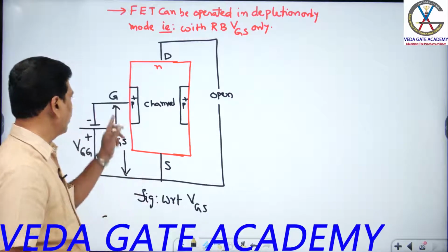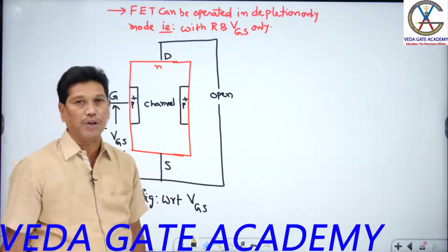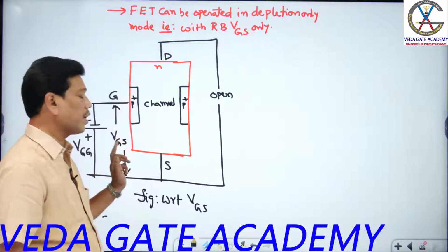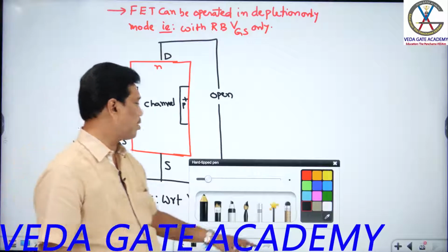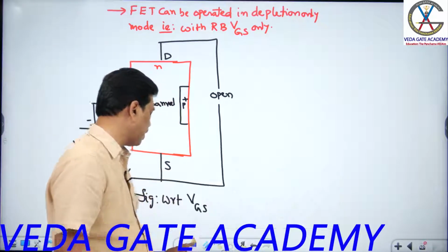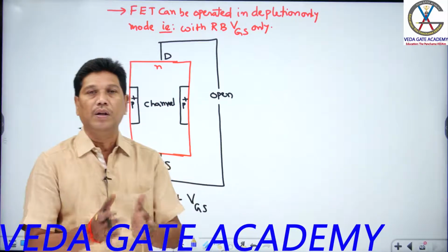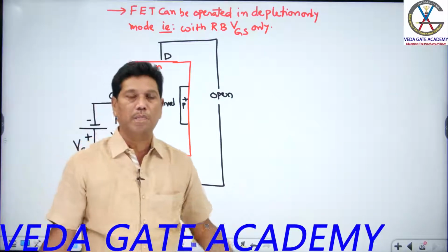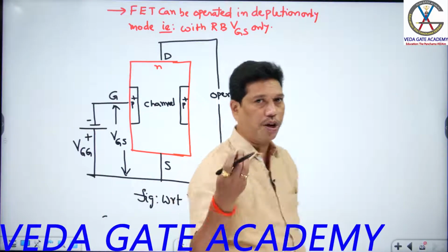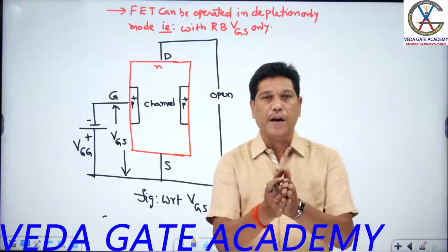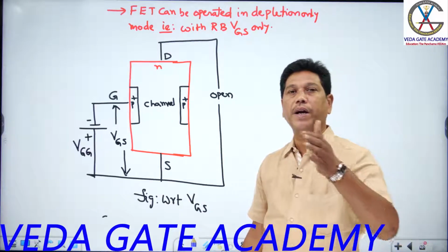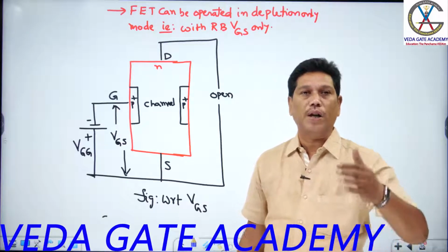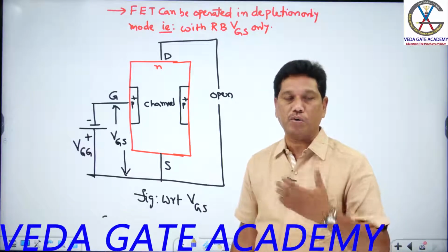See this one now. It is exactly reverse bias on the PN junction, you can call. On each PN junction, it acts as reverse bias, students. So you know the fundamental condition of reverse bias: as the reverse bias voltage increases across the PN junction, the barrier can expand. Simple logic, students. As the reverse bias voltage increases, the barrier expands across the junction. So on what side does this barrier expand mostly, sir? In the lightly doped area, the barrier expands mostly.